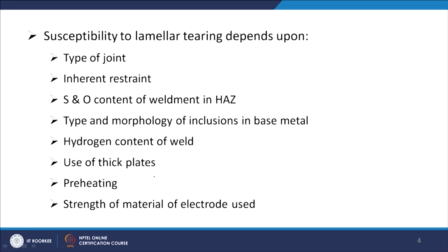So, you have to take certain measures, certain remedies, for the occurrence of these lamellar tears. For that, you use steel with low sulfur content.